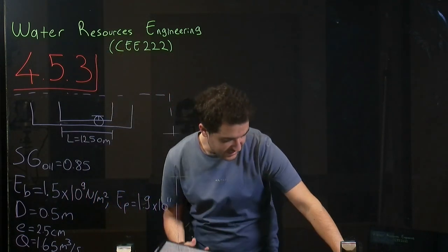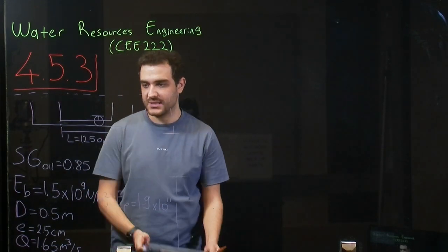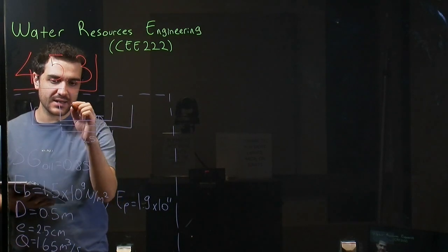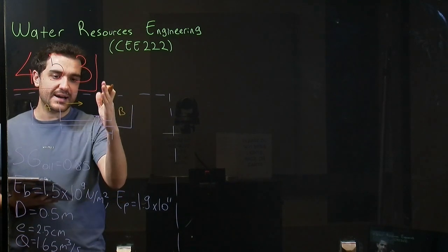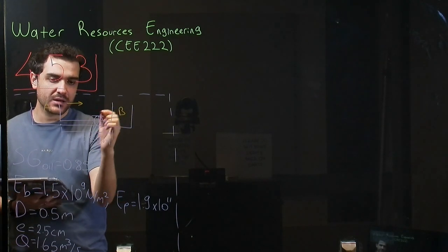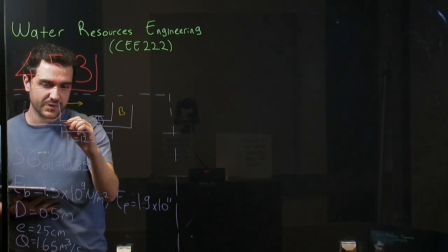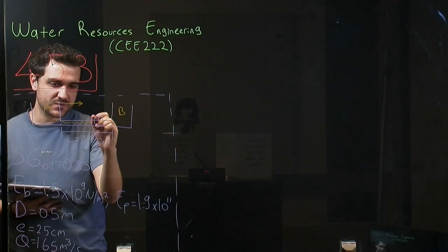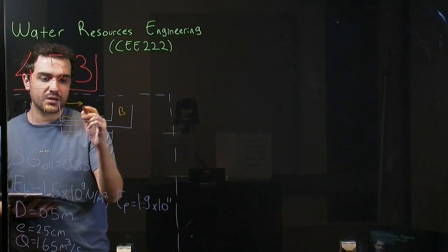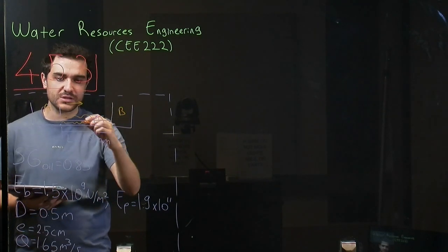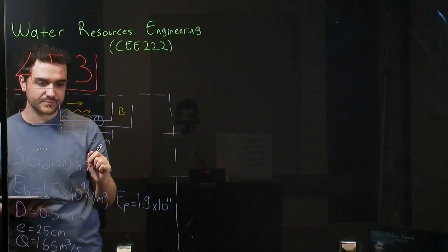So here, this is what happens when we rapidly close this valve. Let's say that we have a flow from reservoir A to B, and once we close this valve, it will cause a pressure wave. This pressure wave will cause water to go back to the reservoir, and then the pressure wave will continue, and after that the pressure will return back to the valve.